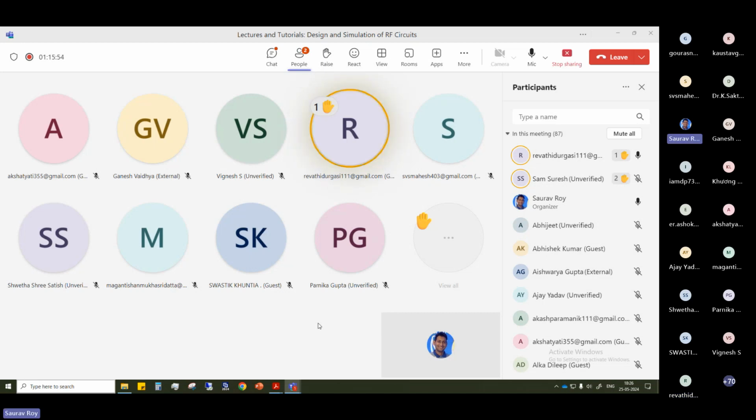See, as I told in the other question, microstrip line can be used for antenna design as well as microstrip transmission line design. In this section we are doing only transmission line design, but there are microstrip antennas also. These are completely opposite things. In an antenna we want it to radiate or transmit, which happens only when you have very high fringing. To have that, you should have a very low epsilon r. When epsilon r is low, the fringing is more, and more wave will be transmitted towards the air.